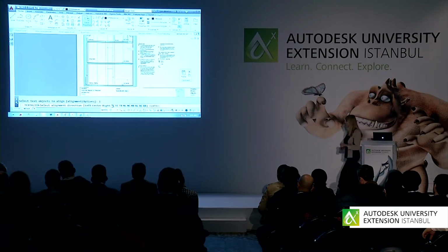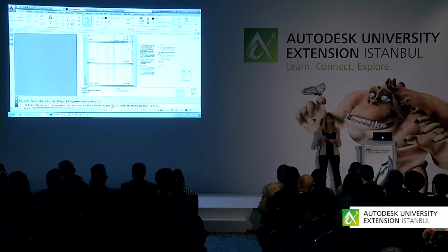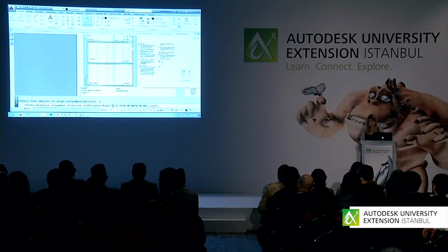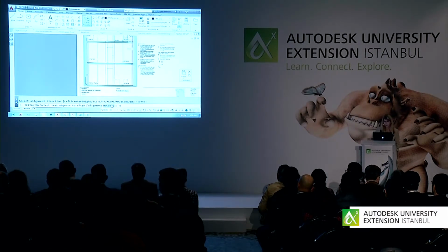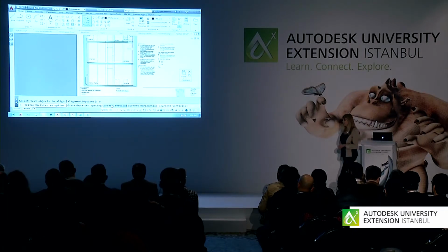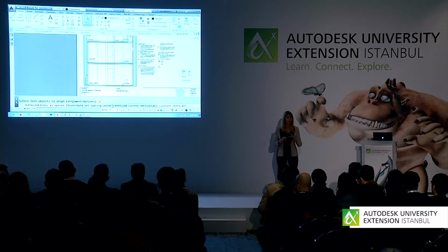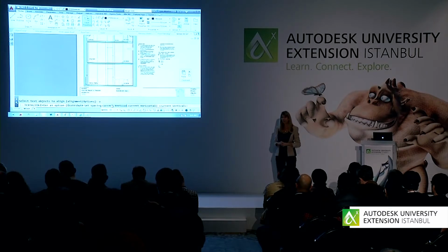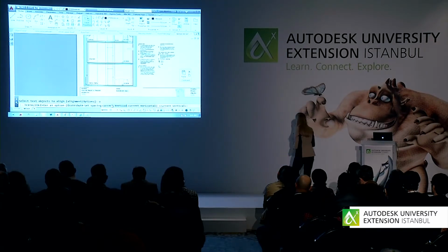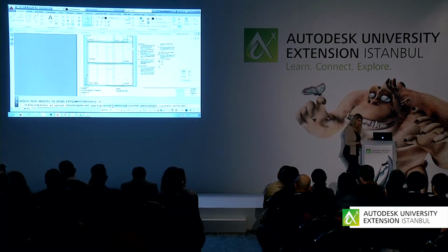So if you take a look at text align, you will see a couple of things. You can tell AutoCAD you want to center the text or right justify the text. You can control the alignment. Or more importantly, you can go into options and say maybe you wanted it distributed evenly. Maybe you wanted it just to grab the Y. Maybe you wanted it to have a specific spacing between it that you can clarify yourself. But that's the new text align command.